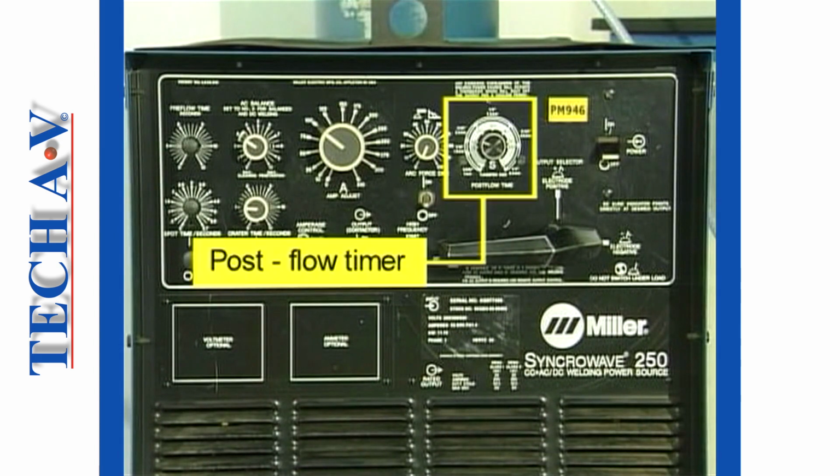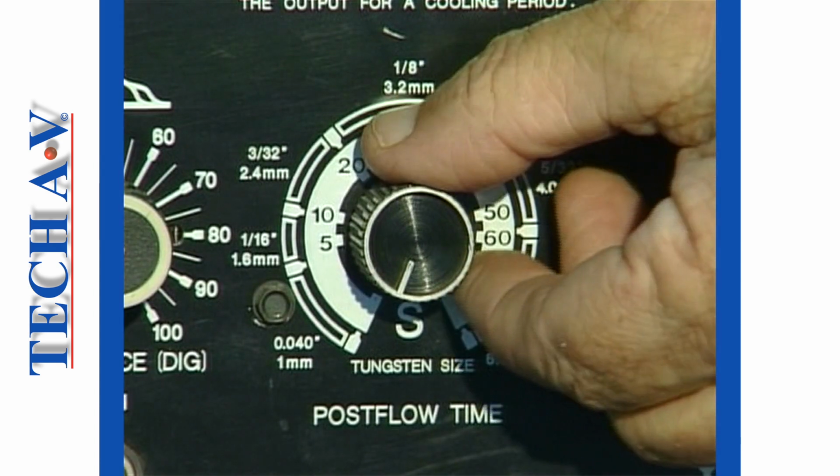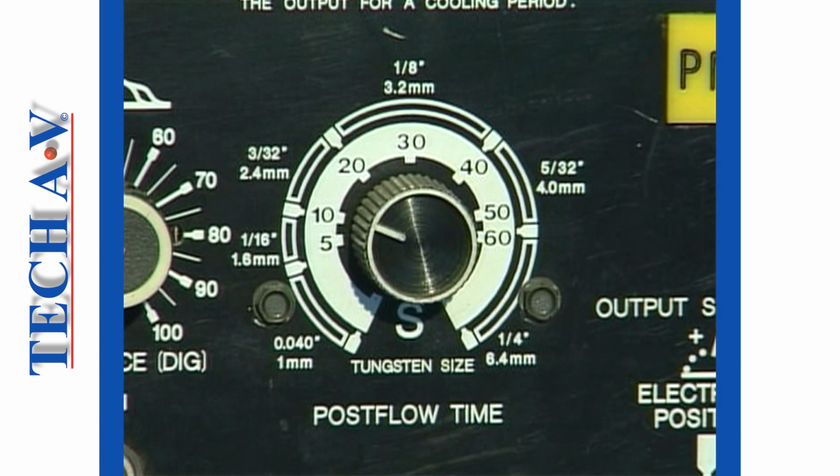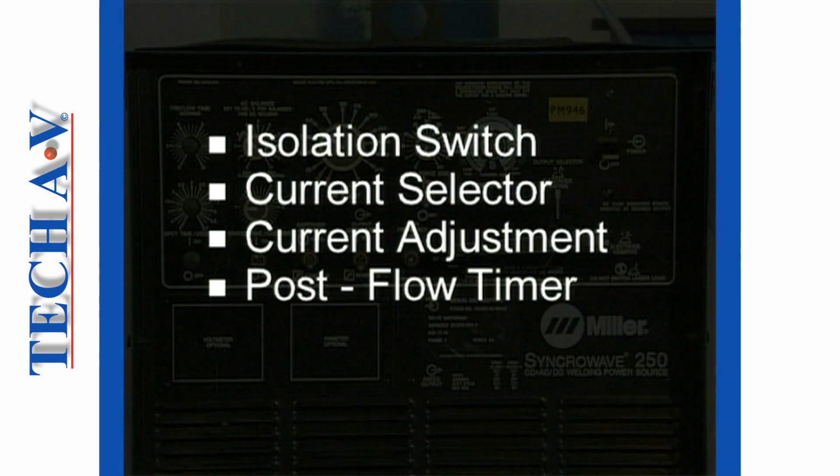The next controller is called a post-flow timer and is used to set the shielding gas. Depending on where the dial is positioned, the shielding gas will continue to flow for the selected amount of time in seconds after the welding current has been shut off. The four controls, or settings, so far mentioned, can be considered as the four basic controls on any good AC-DC TIG machine, as all of these must be preset before any welding can commence.